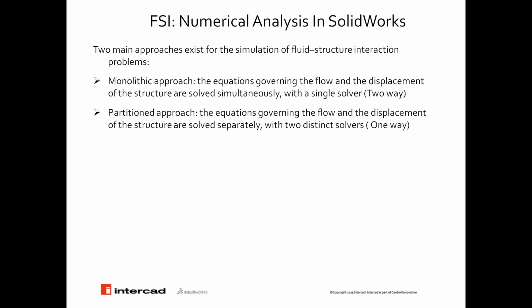The good thing about this is that when a fluid is moving or deforming your structure and a new fluid domain is generated, this type of solver can regenerate the mesh and update the fluid domain after the structure is deformed and updated itself. This scheme is also called two-way FSI. Two domains are solved at the same time, they get their updates, and all results are pretty realistic.